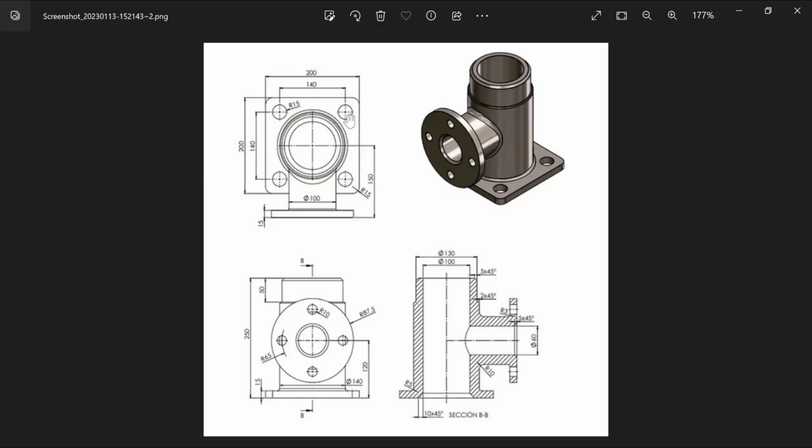From here, this is the top view, so there is a circle for this cylinder, the circle for this cylinder, and also the circle for this inner hole. So you have to hover, you have to be smart. You have to find how you can preview it to get the dimension. The dimension for the inner one is this one, and the diameter for the top is 130.